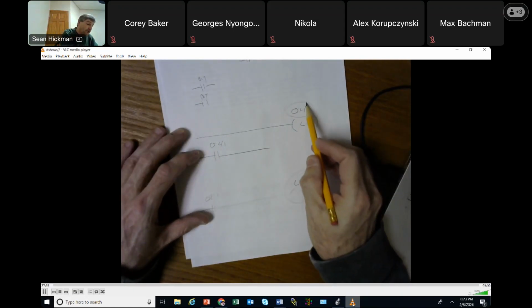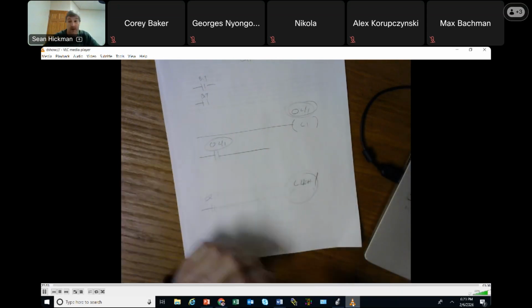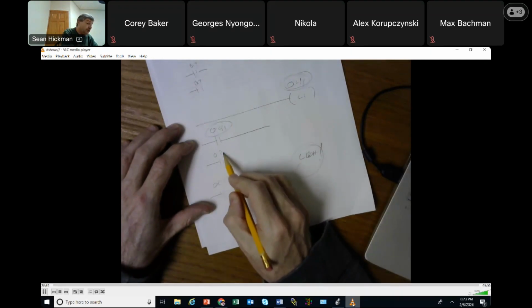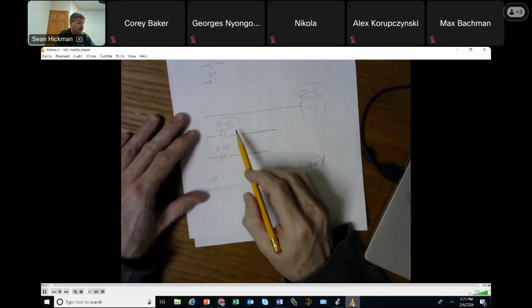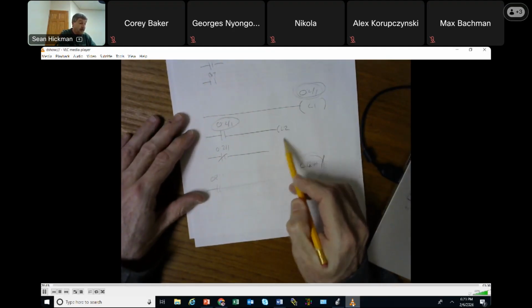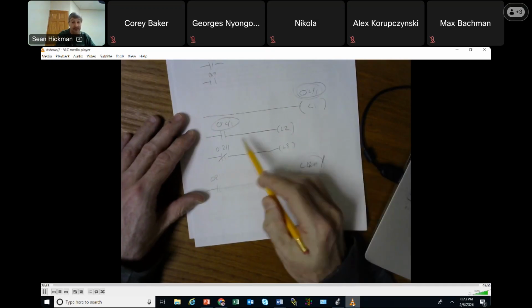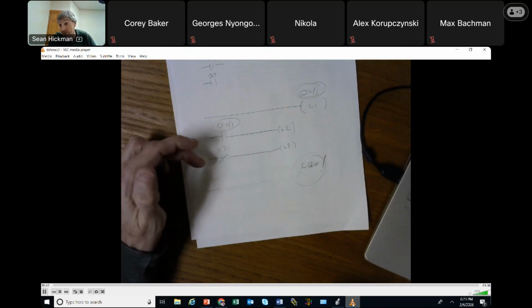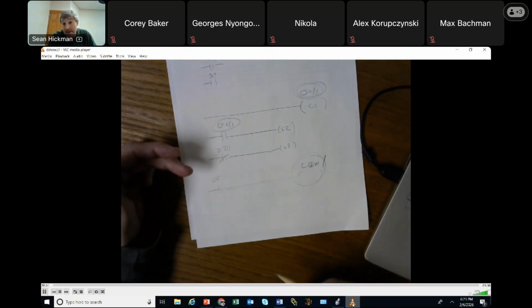So you think this and this are getting updated at the same time because it's the same address. But if I'm going like this and I have output 2/1 here, well, then I got the same thing where I could have both of these lights on at the same time, even though they're interlocked. So maybe you would want to map the outputs as well.